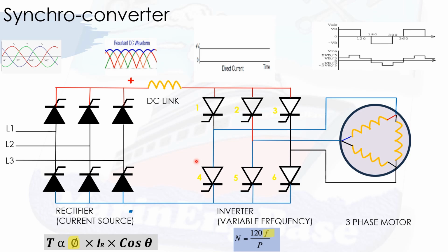Line commutation means that because of the supply frequency, as the current crosses the zero point or gets close to zero, the supply current falls below the holding current of the SCR and it will stop its conduction. So the rectifier bridge commutation occurs as per the supply source frequency. As the supply source current passes through the zero axis or falls below the SCR holding current, each of the thyristors will switch to the off state, and again with the next firing signal it will start conduction.